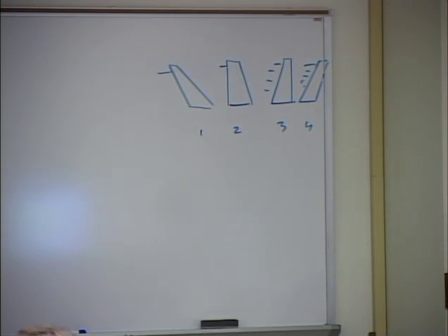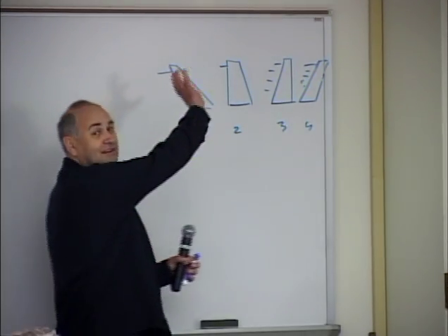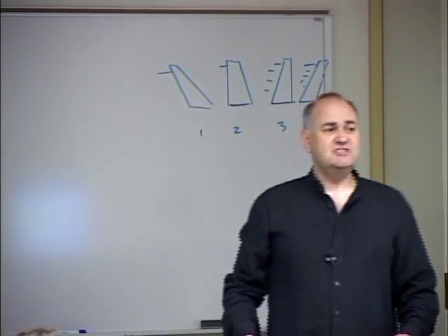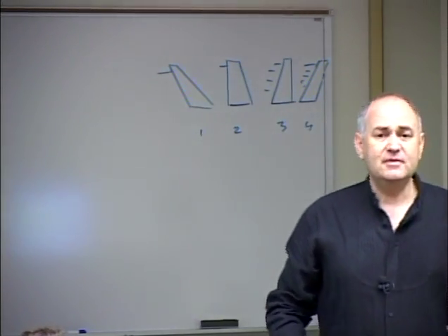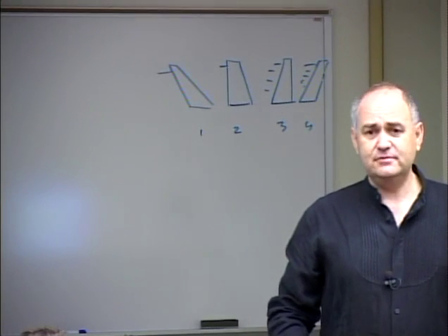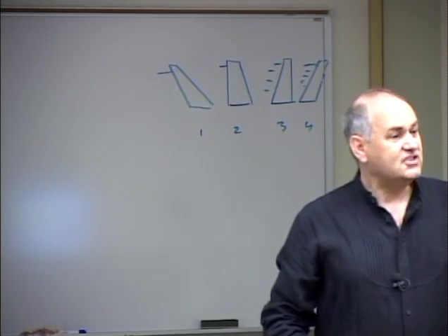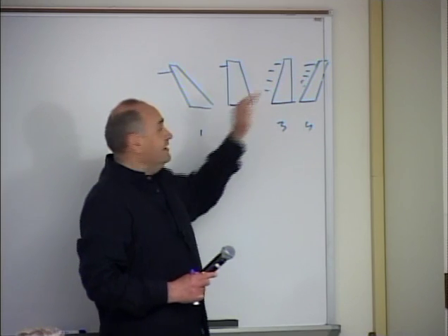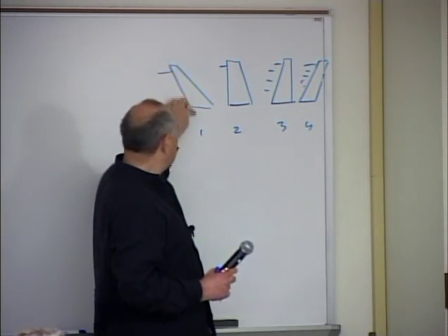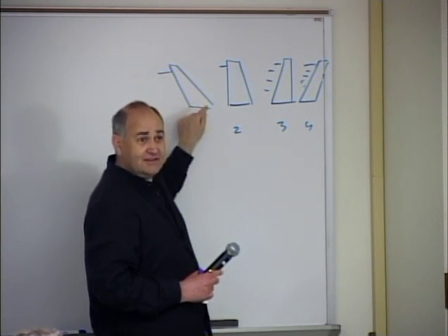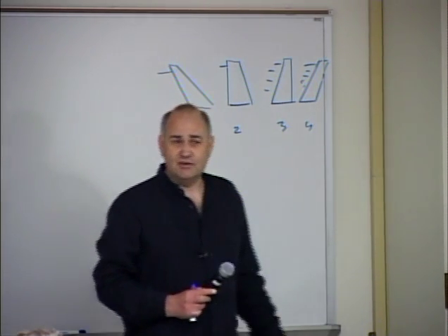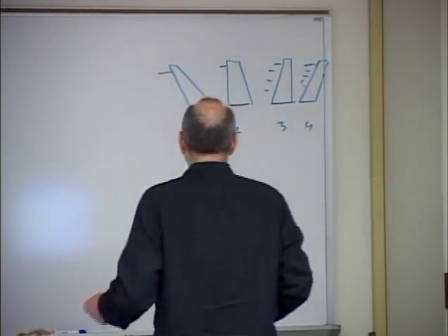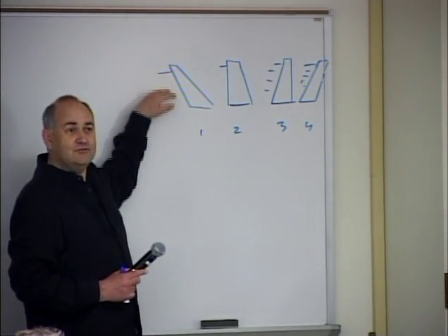Right. Because normally water exerts torque in this side. So if we reinforce the dam, let's say that it is made from reinforced concrete, on which side would we have to put the rods? Inside, on the side of water, correct. No matter which design, if water is up, then the reinforcement should be on the side of water, because this is where the tensile stress occurs. The other side doesn't really need the rods.